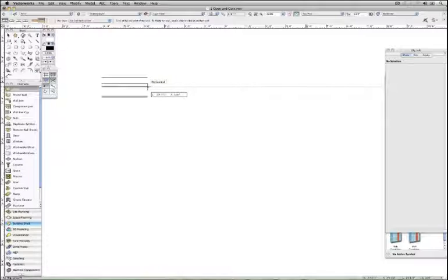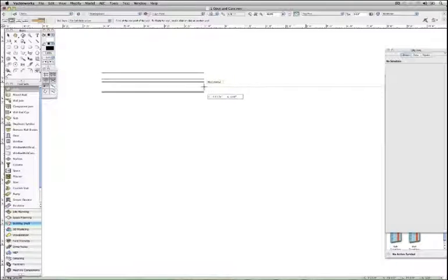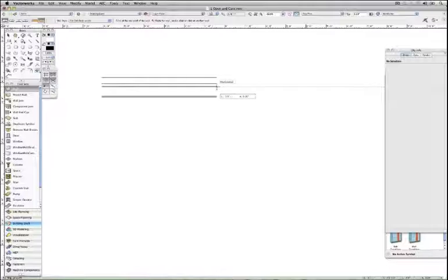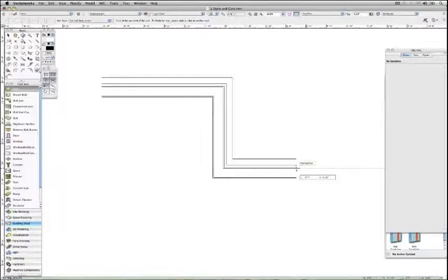This is a fairly typical condition, but in previous versions you needed to do a bit of math to figure out where an offset within the wall would be. Well, not anymore. We can just use the core component control line mode to draw and then subsequently dimension to the face of the stud. While using this mode, keep in mind the U key will still toggle through the three individual offsets, as you can see here. Okay, that's good.